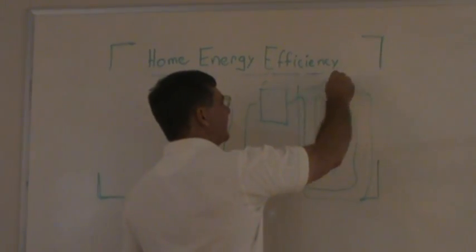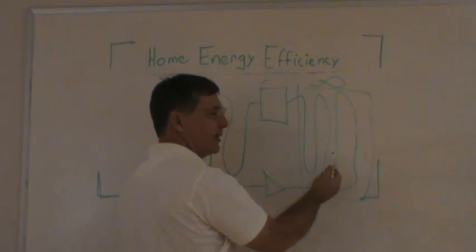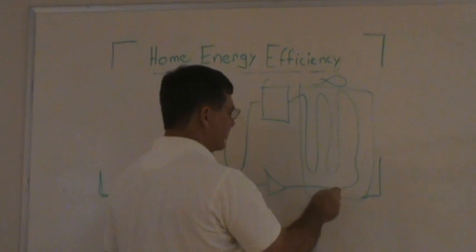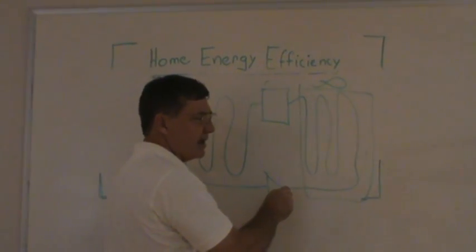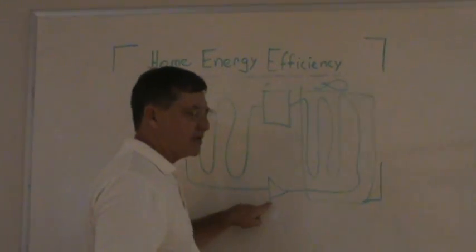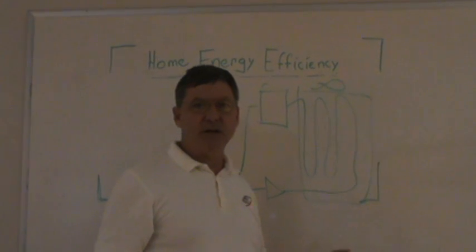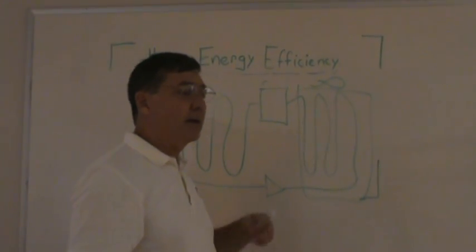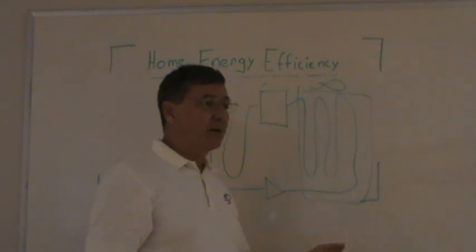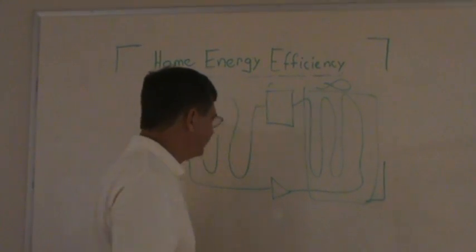And we can put a fan here, draw air across it that takes the heat out of the condenser outside and puts it into the air. And then when it's dropped enough heat, it turns into a liquid and it goes into a metering device. There's really three kinds of metering devices typically found in residential heating and air conditioning systems. Cap tubes, which are found in refrigerators typically. There's pistons, and then there's TXVs.